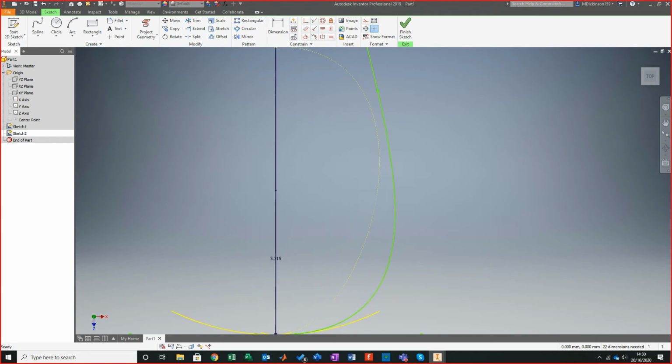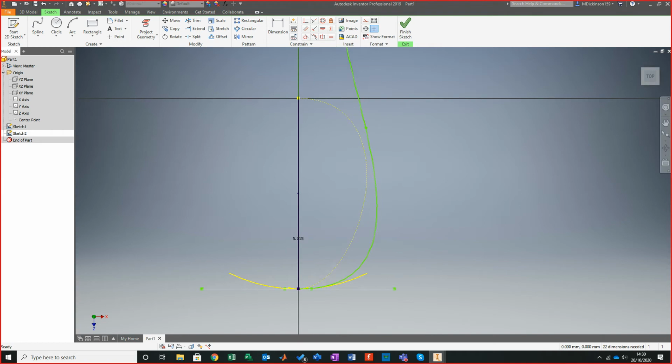Right, so you see now this construction is in control of this spline. So I'm going to bring that back in. Now look, I forgot to make this vertical. Let me just check that I am looking at a vertical in this case. Let me check. No, we're going horizontal in this one because again it's on this datum it's referring to, which is a weird experience I do appreciate. Right, that's better. So now if I move, I can only move in that component set, which is ideal.